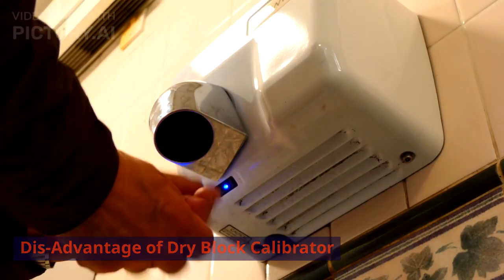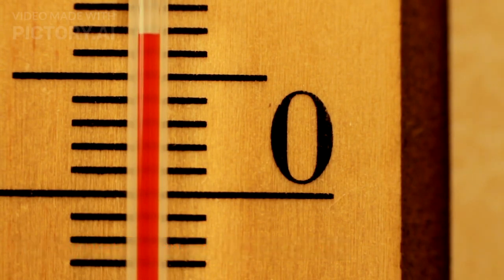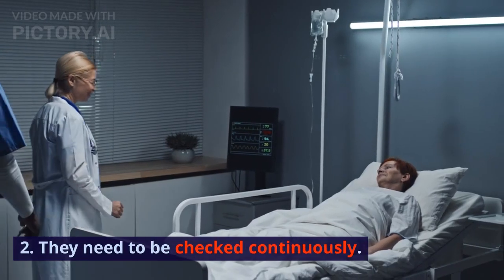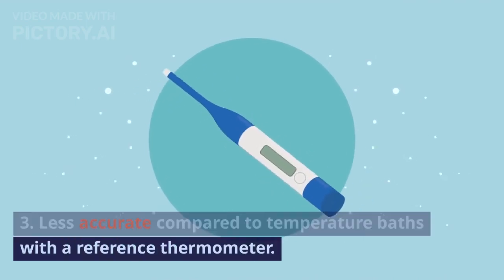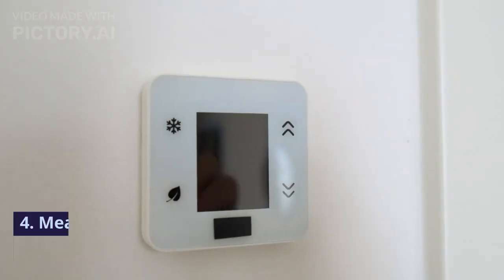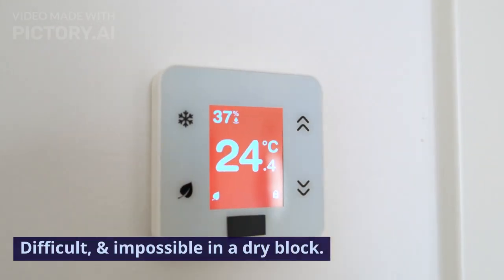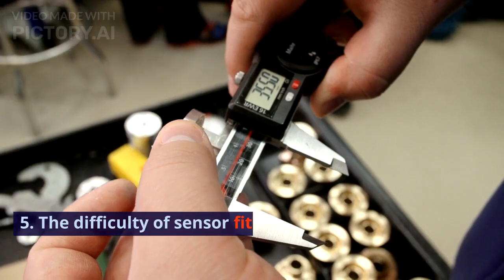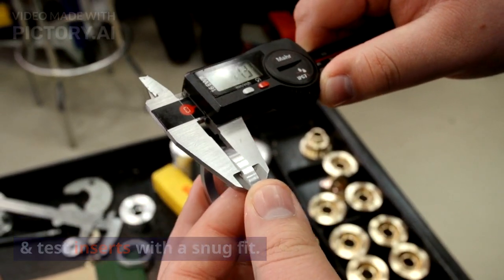Disadvantages of dry block calibrators. 1. Temperature sensors drift over time. 2. They need to be checked continuously. 3. Less accurate compared to temperature baths with a reference thermometer. 4. Measurement of odd-shaped sensors is difficult or impossible in a dry block. 5. The difficulty of sensor fitting in metal blocks and test inserts with a snug fit.